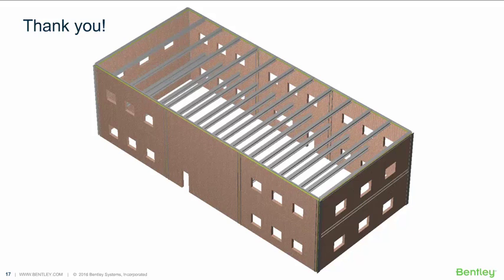In RAM structural system, if we have two stories here, the lower one being where that joint is and the upper one being the roof itself, when you enter into RAM Frame, it wants to treat it as two different stories. It sees though that there's no diaphragm laid out at the lower level.